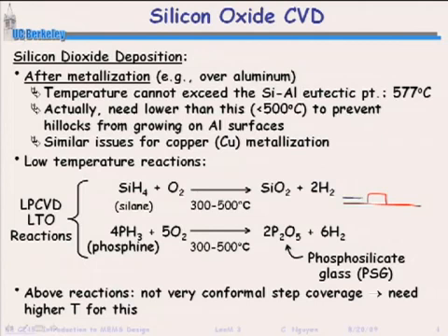We'll learn later on that we don't like topography, because topography is going to make it difficult for us to do lithography. It's going to make it difficult for us to do etching. So if we can avoid topography, meaning large aspect ratios, we want to. One way with phosphosilicate glass that you can do that is you can heat this thing up to 1050 or so, 1 hour at 1050 degrees C. And if you do that, then what happens is this phosphorus layer will smooth out.